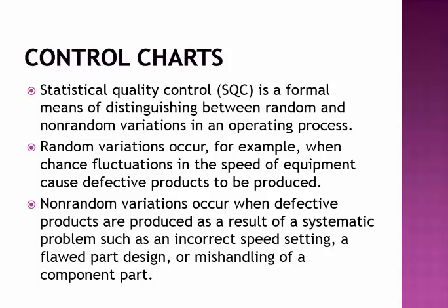Alright, so what we're going to do is graph the data. You should have already seen in your stats class how we can gather this information. We're going to call them observations, and we can literally plot them out on a chart. We are going to have an upper limit and a lower limit, and we expect our production process to have items within those limits. If we have anything go outside of those ranges, then we have something that we need to take care of.